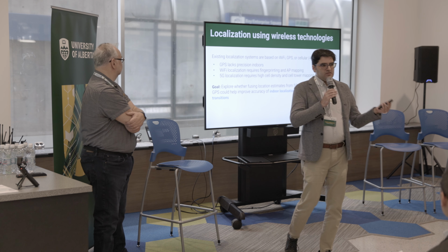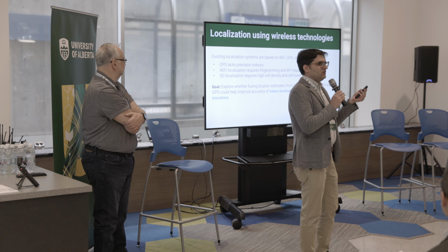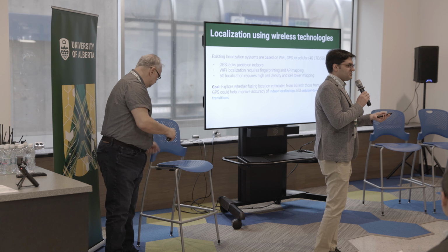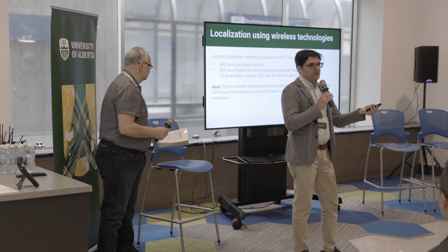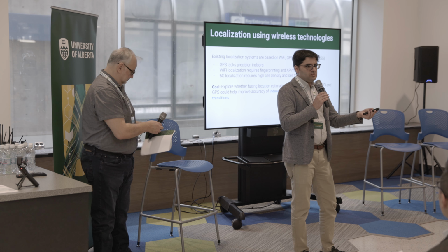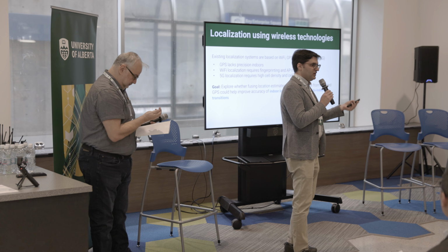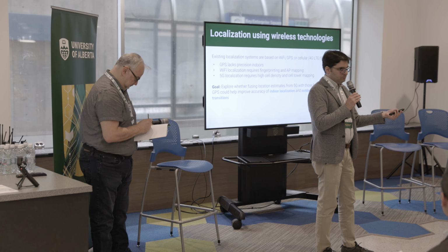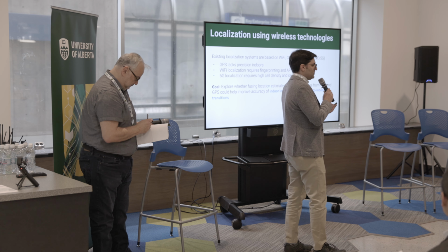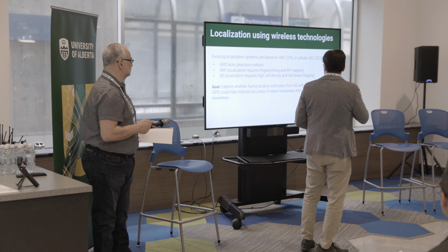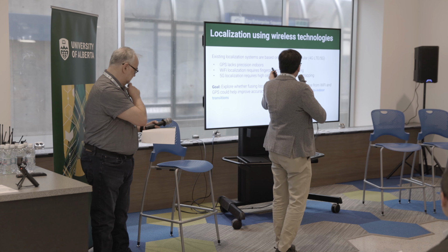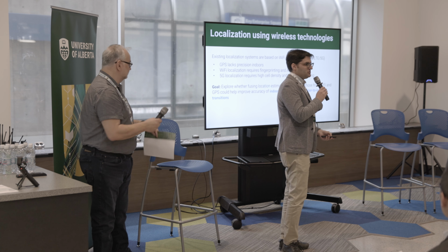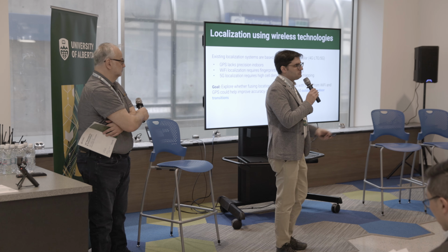And the reason I'm saying that these are virtual sensors is that they are not actually deployed there to get a sense of the occupancy state of the space. These are perhaps Wi-Fi access points, 5G antennas, cell towers that are there in order to provide internet access to people. But we can use this data to get a better understanding of the occupancy pattern of the building. So this can be done using different approaches, Wi-Fi, GPS, and cellular technology, 4G and 5G.